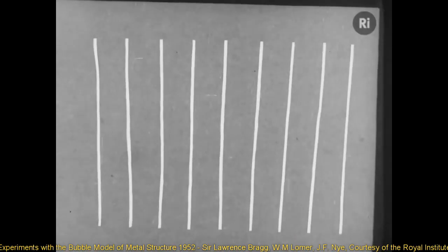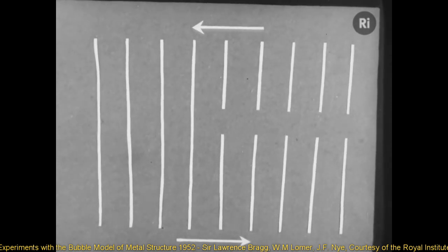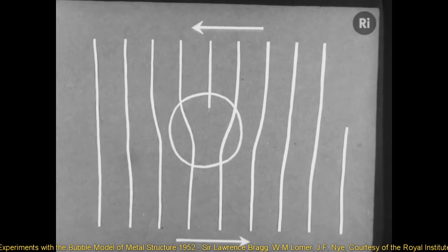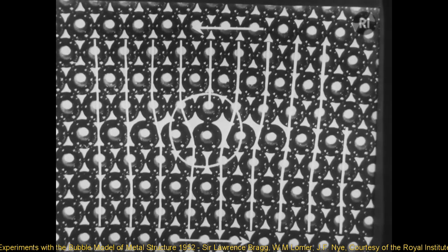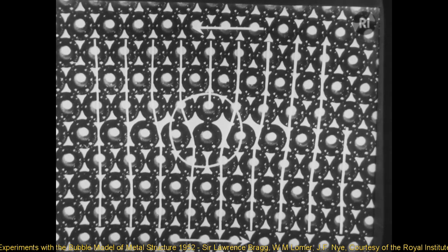Dislocations occur when atoms are displaced one-dimensionally, or along a line, like an entire row of atoms being in between the normal atomic sites. Bubbles are particularly good at modeling edge dislocations. Here you can see where the extra line of atoms starts, pushing aside the existing rows.